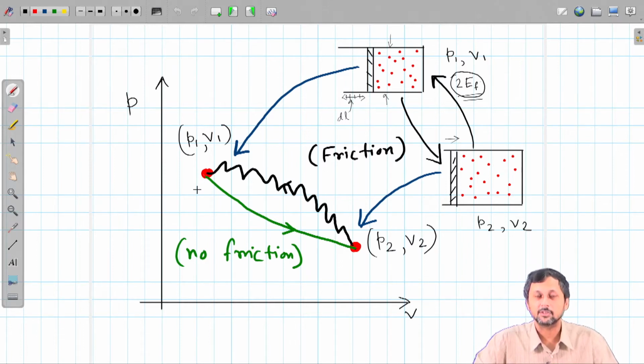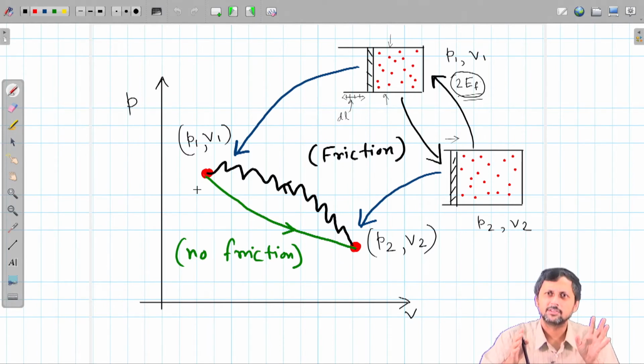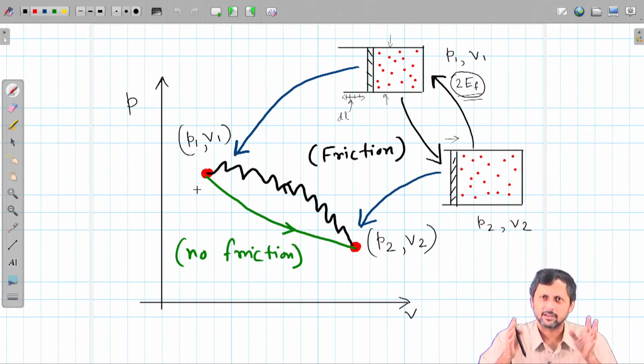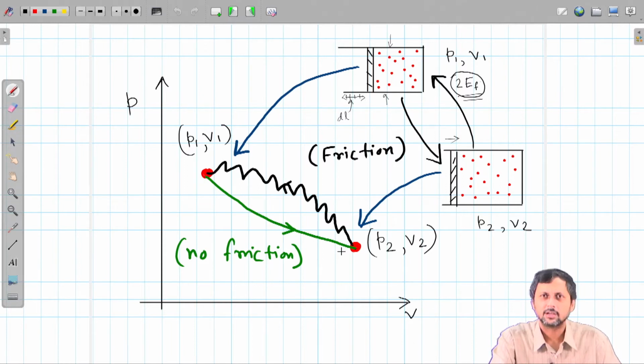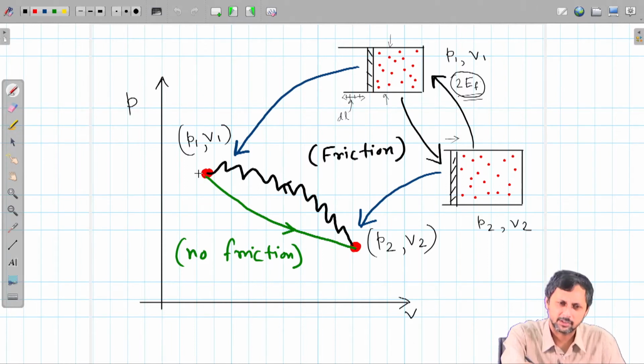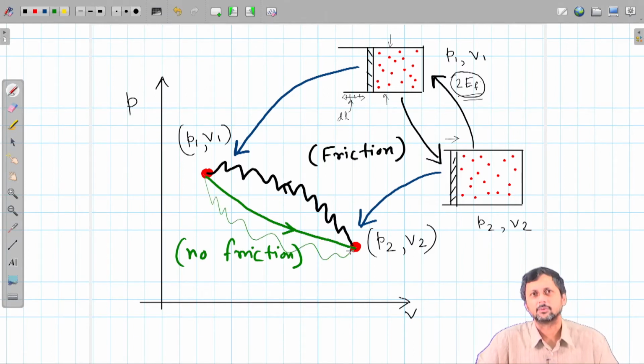Now, in an irreversible process, the exact amount of energy dissipated can be calculated, but the only thing is it cannot be reversed. What I mean to say is, even if we reverse the process, that dissipative energy will still be lost once again, and the total change in system plus surrounding will be non-zero. So, I intentionally made one part of it in a reversible manner, the other half in an irreversible manner, but in reality for any process both these sides are irreversible. Both the forward process and the reverse process are actually irreversible.